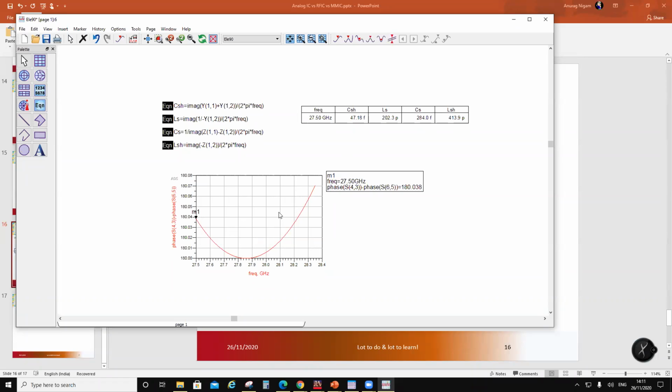One side has to be high pass and the other side low pass, so that the difference remains constant. If you take two low pass elements, they will be unequal, and the phase delay will not remain constant, so you will not get the bandwidth. You need a high pass and a low pass equivalent.